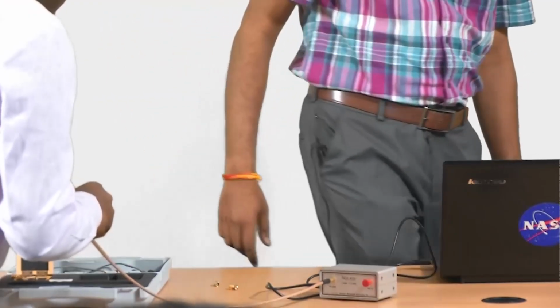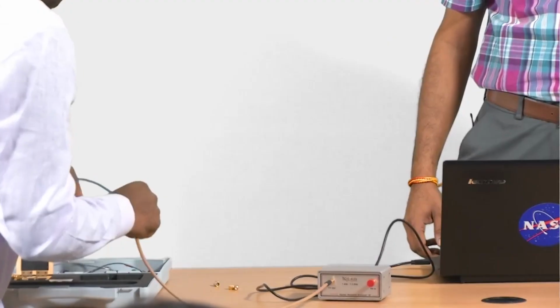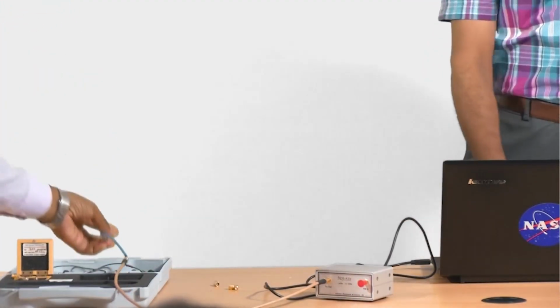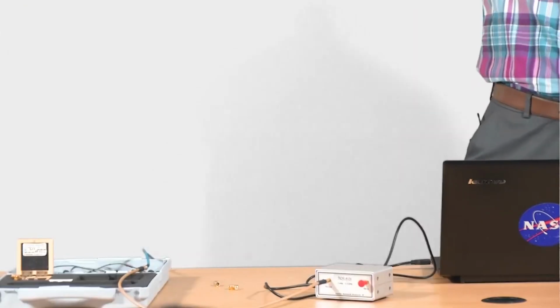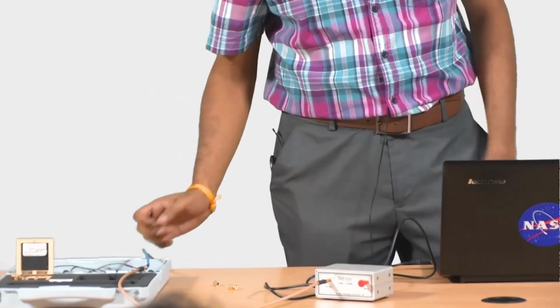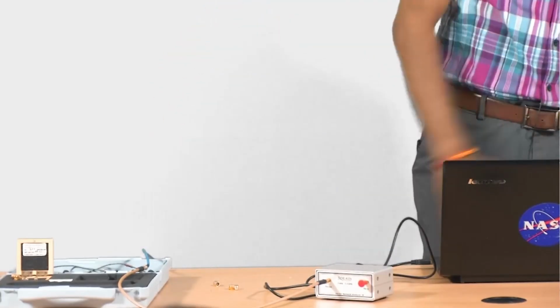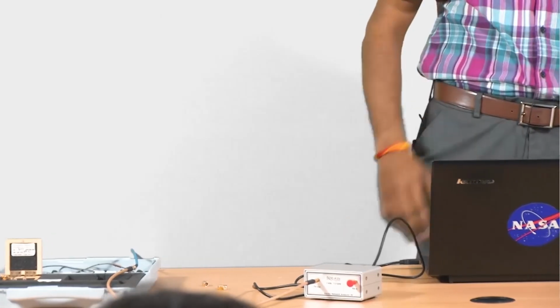So he is adding a small section to it. Total length. Okay, so he is having a different length. It went to a different place. So now it should be clear that depending on the length of the transmission line, you will be traveling around in constant VSWR circles. So we are sweeping a constant VSWR circle.